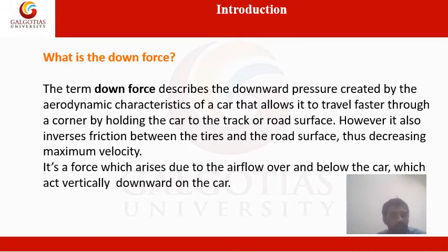Because it is a function of the flow of air over and under the car, downforce will increase with the square of the car's speed, and it will require a certain minimum speed in order to produce a significant effect. So this is again one of the important things to note.